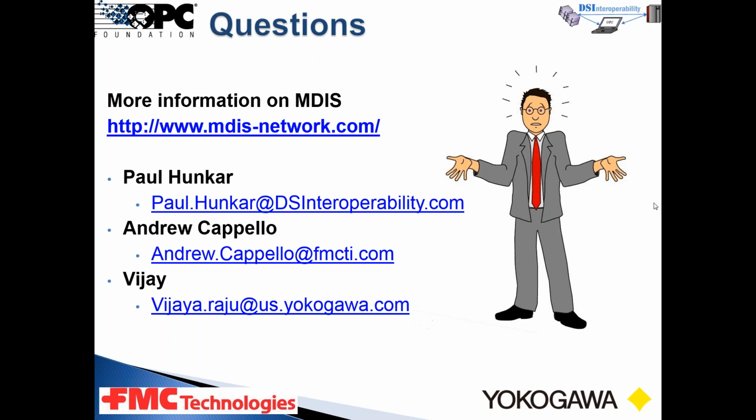Yes, this is Vijay. Actually, with Modbus, all the communication happens in bits and bytes. So configuring a system which works on Modbus is quite cumbersome. Versus OPC UA, where you can actually standardize the objects. OPC UA forms the object model, so you can standardize the objects at the server side and the client side. Once you have standardized, connecting both the client side objects and the server side objects is quite simple. Okay, thank you for that answer.